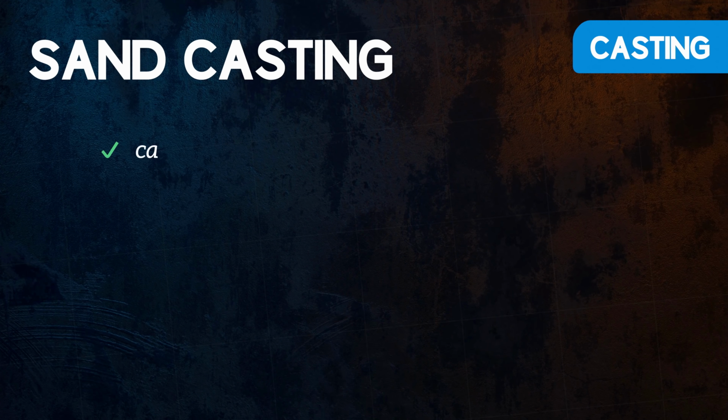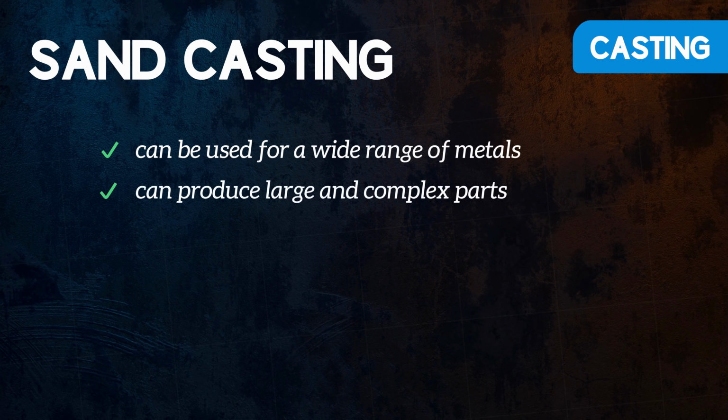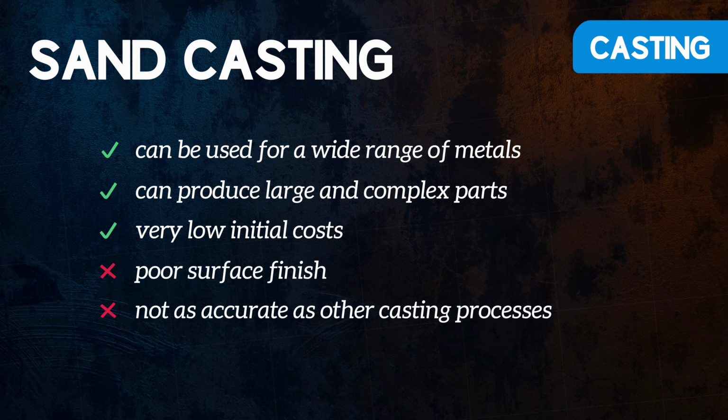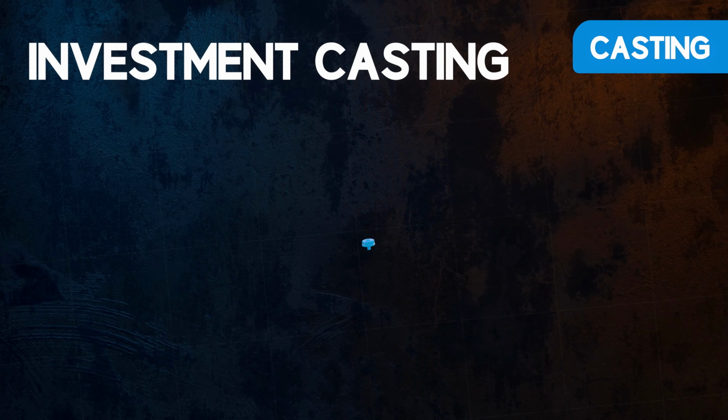Sand casting can be used for a wide range of metals, including those with high melting temperatures. It can produce large and complex parts, and initial costs are very low, making it good for small production runs. However, it provides a poor surface finish and is not as accurate as other casting processes. The last casting process we will look at is investment casting.